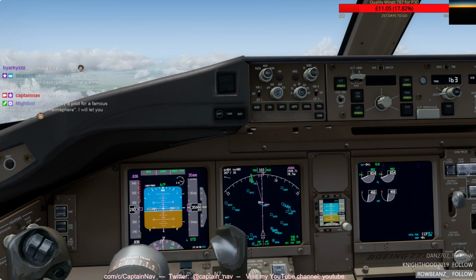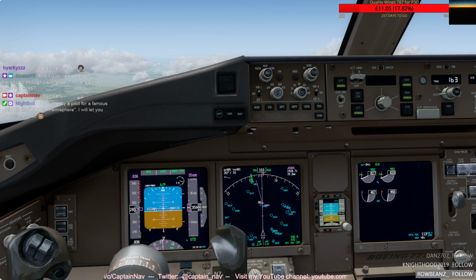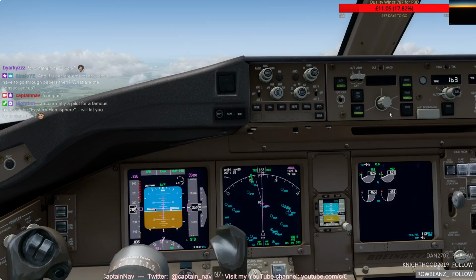So before you get into a fuel emergency situation, you can call and say, okay, I'm on minimum fuel, so that means to air traffic control that any changes to the current clearance, whatever the situation is... For example, you're on downwind, you expect a turn to base soon and then to establish on the ILS and land. If there's any changes to that, then you might go into the final reserve, the last 30 minutes, and then get into a fuel emergency. So you can say, okay, minimum fuel, so they know.